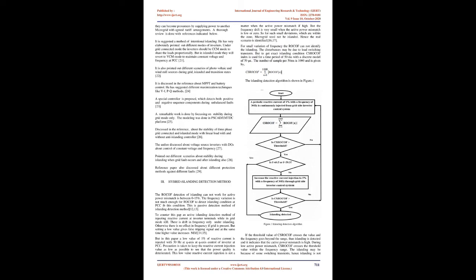Islanding detection is more crucial, as a safety aspect and stability concern is involved. If there is any fault in the main grid, it is to be sensed and the microgrid has to switch over to islanding mode seamlessly so that there is no interruption of power to the microgrid loads, which are termed essential [3, 4]. These are also called unintentional islanding. Intentional islanding is when maintenance work is to be performed either on the grid or microgrid, and the microgrid is to be isolated from the main grid. This isolation of the microgrid is achieved through a hybrid islanding detection technique of both passive RCOF and active reactive current injection at inverter terminals.